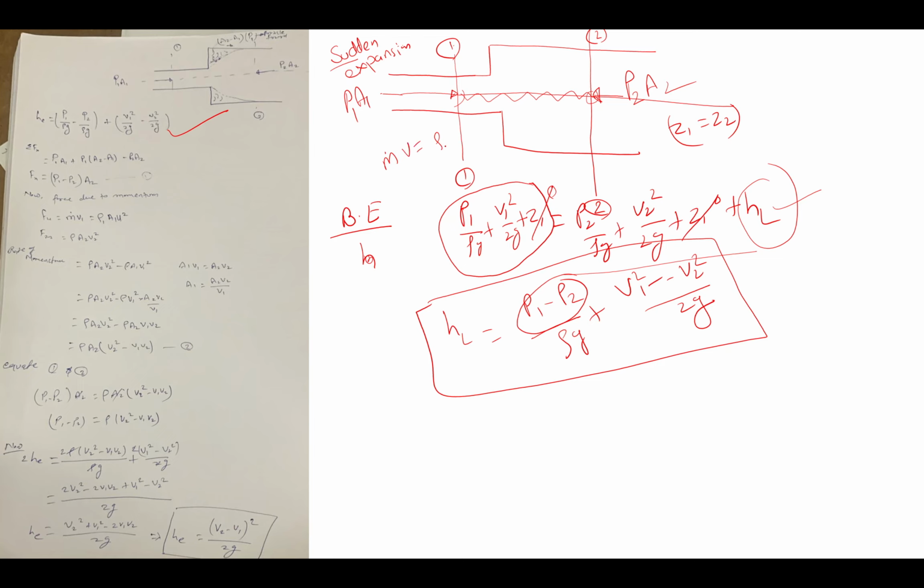The fluid density is constant, that is an incompressible fluid, obviously, because you have applied Bernoulli's equation with its assumptions. If you are applying Bernoulli's equation in any question, you by default assume all the assumptions. So rho A v for m dot, the mass flow rate, and another v also, so here rho A1 V1 square, here rho A2 V2 square.